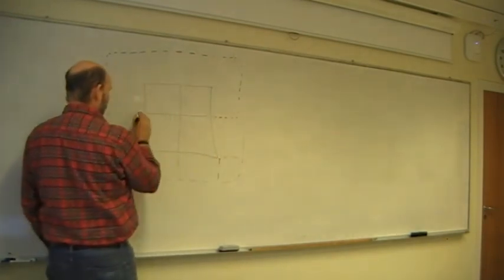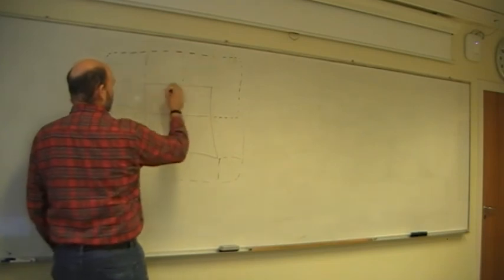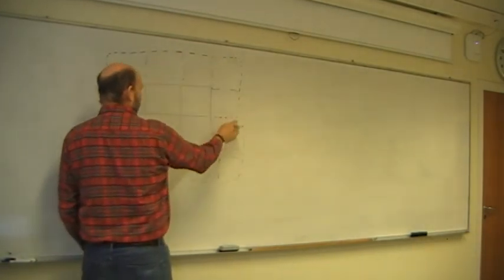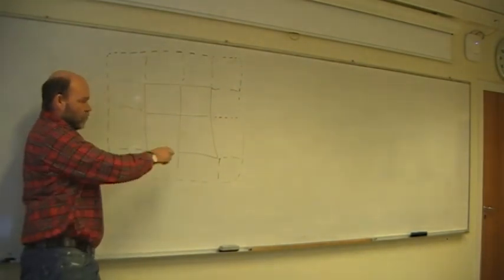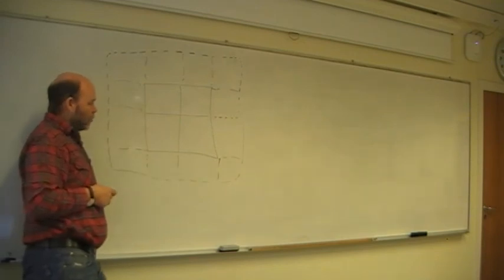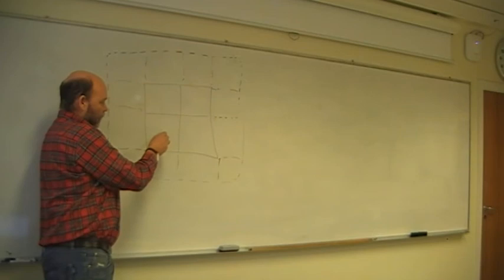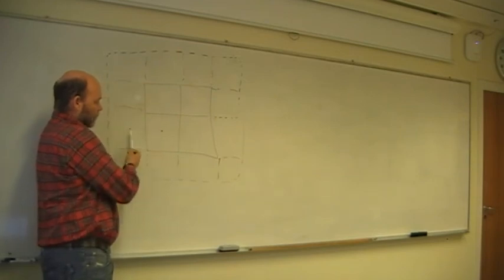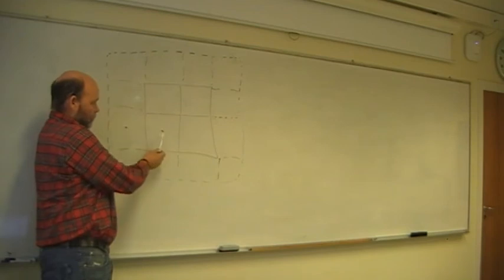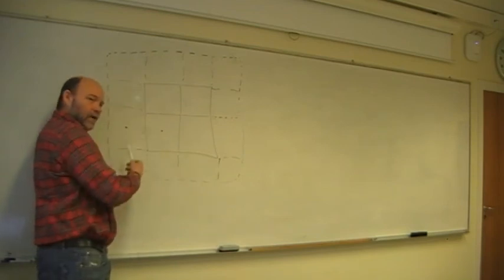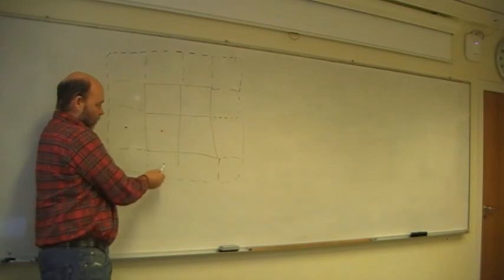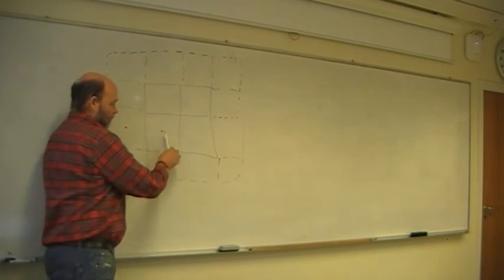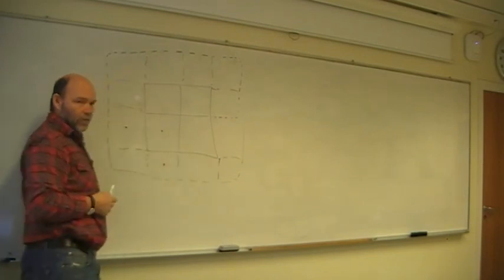And then use the boundary conditions using these ghost cells. Or, if you want to do it more correct, you don't use these ghost cells, but you have to program your boundary cells accordingly. So if you have a Neumann condition here, saying that the pressure outside should be equal to the one inside, then you have a sort of special version of your discrete equation system for these points. And this is also a corner point, so you also have to do it here. But here you have the ordinary derivatives and double derivative expressions.